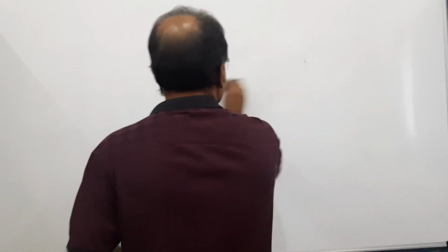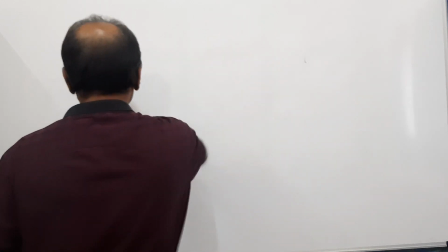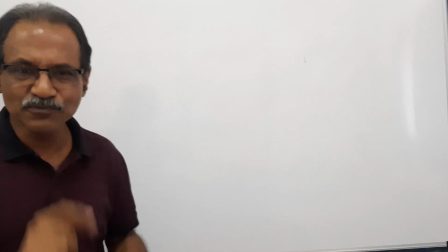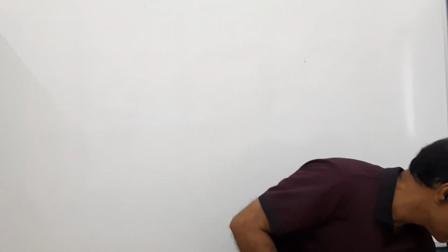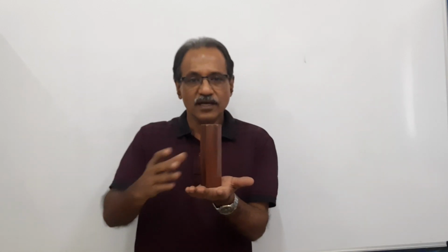What is the plan of a hexagonal prism resting on its base on HP? It's a hexagon. In this particular problem, when a hexagonal prism is standing on its base on HP like this, or when it is lying on HP on a rectangular face, or a pentagonal prism standing on its base on HP or lying on a rectangular face, in such cases you have to draw plan or elevation depending upon the orientation, and from there only you can come to the isometric view.